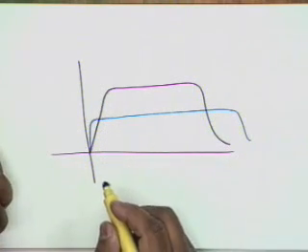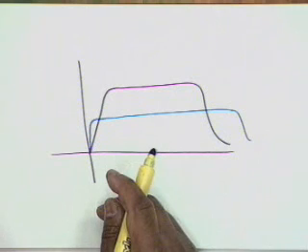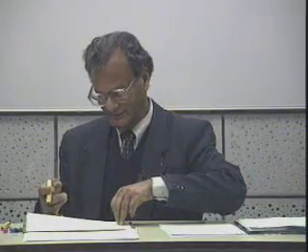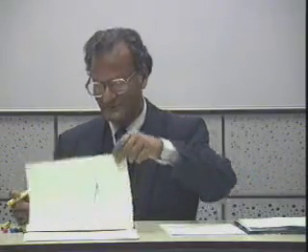The bandwidth increases by the same factor as the gain reduction. So what you gain in bandwidth, you lose in gain. So the pre-amplifier stage should have a gain of 1 plus A0 beta. That's right. The pre-amplifier stage should have a gain of 1 plus A0 beta to be able to bring the gain back to the previous quantity.